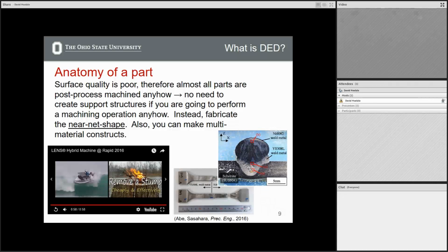Composite materials are hard to talk about. Not really doable with powder bed fusion because you're scraping this powder across the surface and you have a lot of mixing when you do that with the recoater blade. And you would also never be able to separate those materials afterwards if you ever wanted to reuse that material. It's impossible unless you had some sort of magnetic difference or something, or you can separate them. It'd be very difficult. But you can actually pretty easily get composite materials. So here's the interface between the two of them, which makes for some interesting things. I haven't seen too much about this yet, but I think there could be some definite opportunities there for things to do.